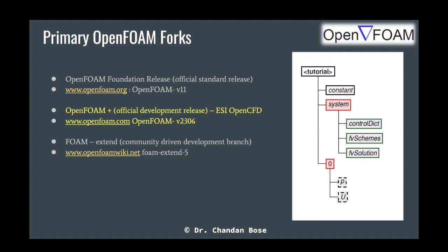Yes. And then if you want to run it in parallel, is the code directly parallel or do you have to...? Yes, it's a good question. So the code in the OpenFOAM library is written inherently in a parallel way. So you just have to use an appropriate domain decomposition technique. And to solve the solution in parallel, you have to use the MPI library.